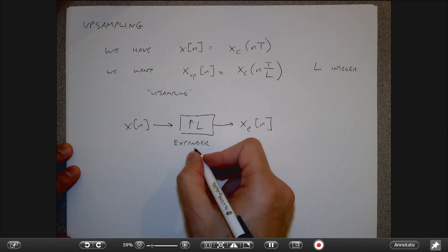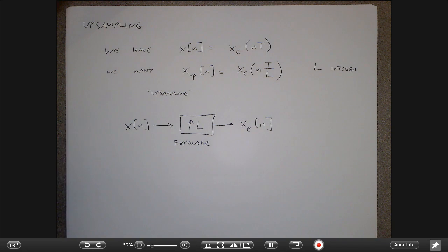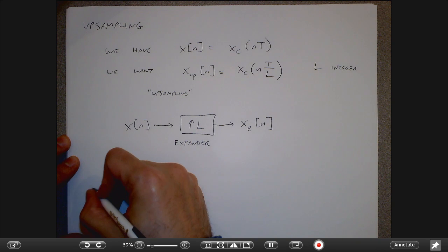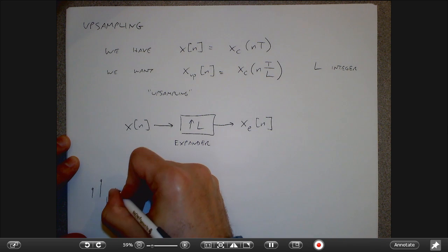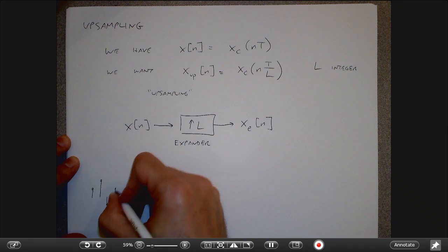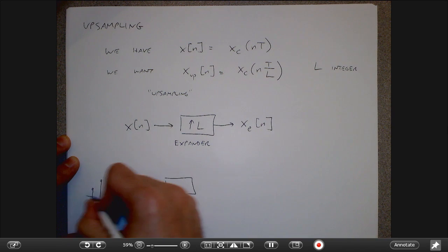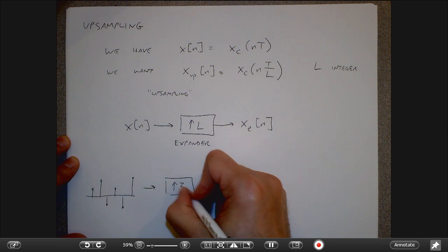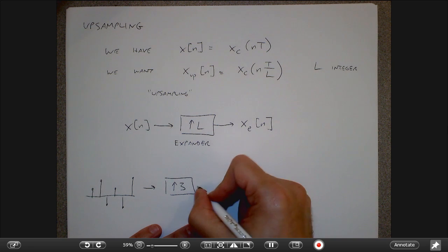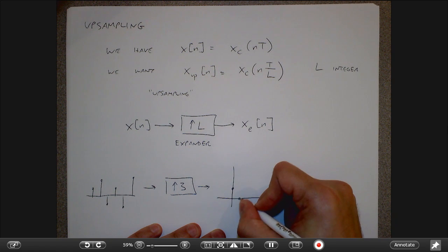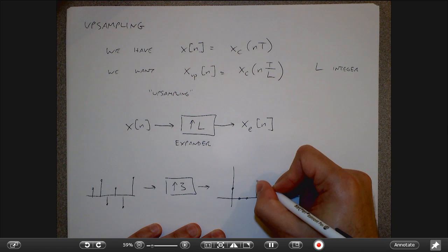Well, this guy is going to insert zeros between my original samples. So, for example, if I have a set of original samples, and I put it through an upsampler by 3, then what happens is I get the original samples, and then between every pair of samples I get a couple of zeros.